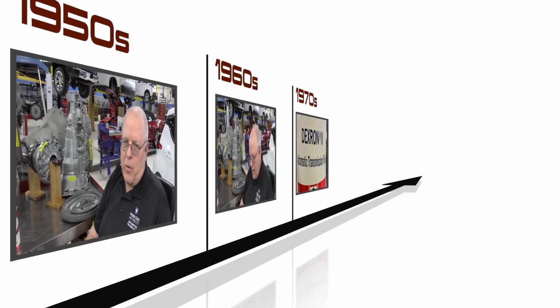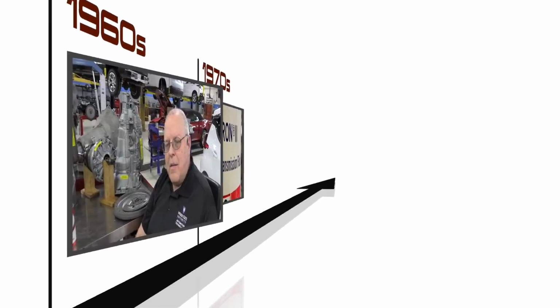Now, by the 1960s, oil refining had improved. The Group 1 base stock oil that all of these transmission fluids have been comprised of, along with additives being added up to this point, was refined with something called solvent refining and dewaxing. But a new process called hydrotreating would help make the transmission fluid more stable to where it was less prone to oxidation.